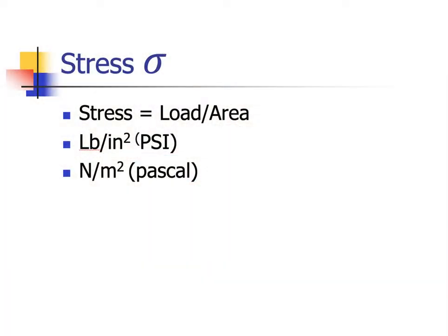So that same theory we could apply to some measurements and some math. Stress is equal to the load over the cross-sectional area, and that's the reason, because if I put 10 pounds on that small diameter wire, it breaks.